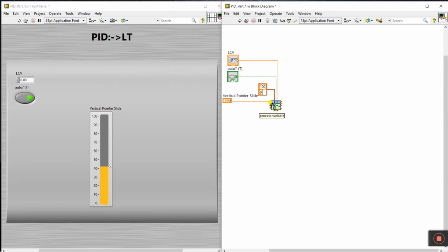It depends upon your output. Now we connect the output and data terminal. This one is PV, process variable. We are connecting it to the output of our plant. Now ignore this. The next one is set point range. No need to enter a set point range because we already entered it here. This is the maximum, this is the minimum. No need to use this set point range.